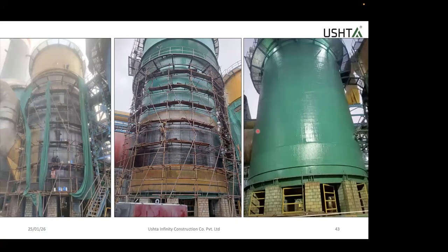And we have given an operational guarantee of 5 years on this. On the right hand side, what you see is the repaired tank. So in this, unlike the pipeline and the tube, this is not a standalone repair, but this is a compensating method. So whatever is damaged, we are only compensating that much thickness. And that's how we have given a guarantee of 5 years and not more. Right? So we are only catering to the loss which has occurred due to the thickness loss.